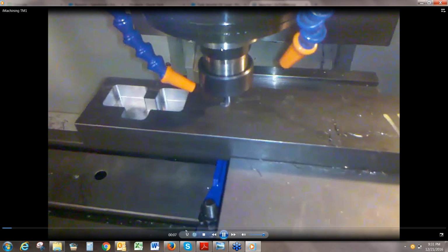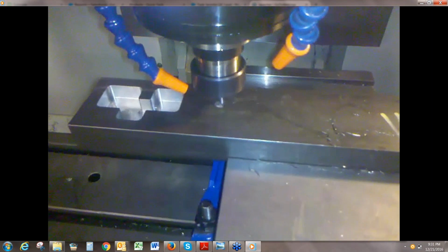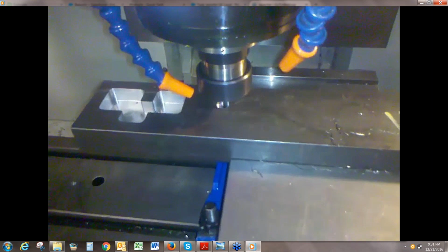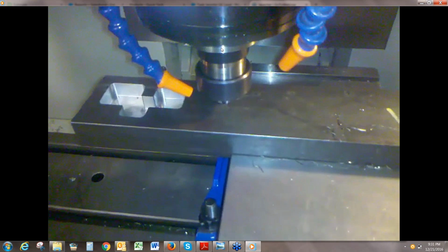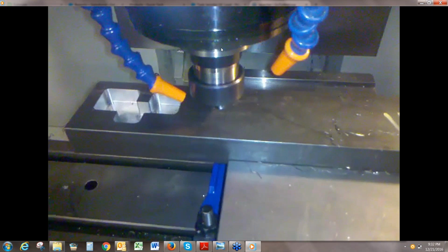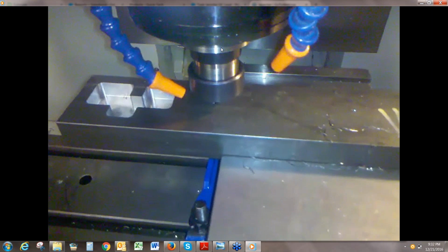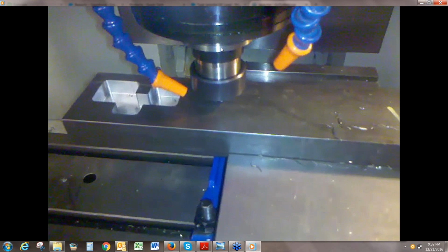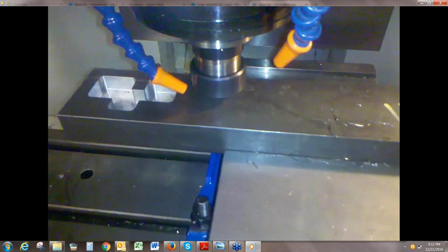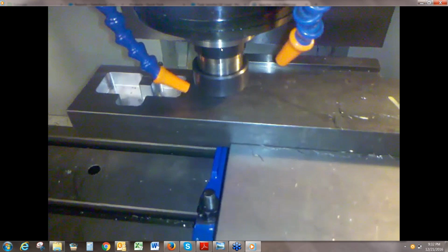This machine, I think the maximum programmable feed rate was 50 inches per minute. Loose spindle bearings, loose ball screws, and that first pocket, he did it at 50 thousandths depth of cut. It's 1 inch deep. What was it, 4 hours and 20 minutes? No, it was right around an hour, and he would have to take it down in 50 thou increments. By the time the tool got to the bottom, it was actually shot. You'd have to come back with a face mill.